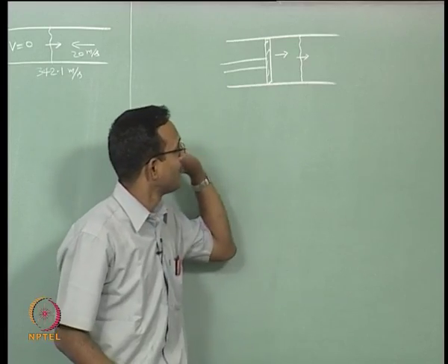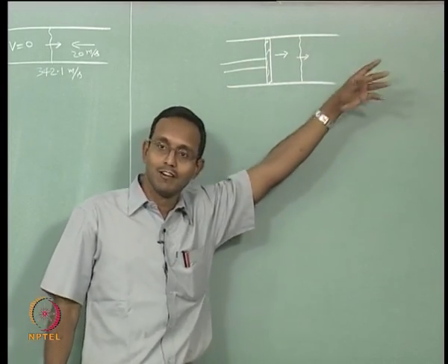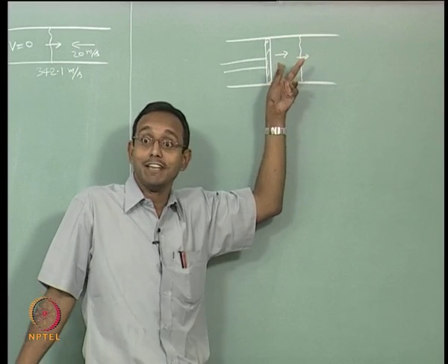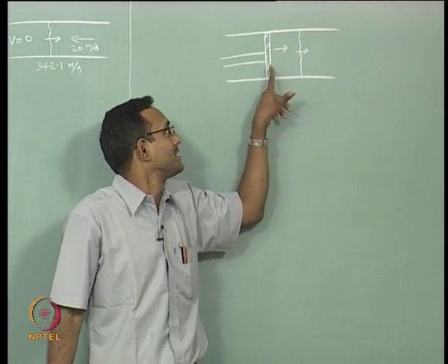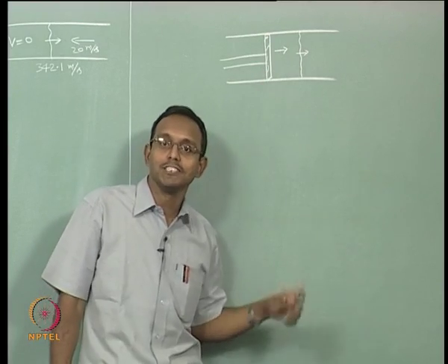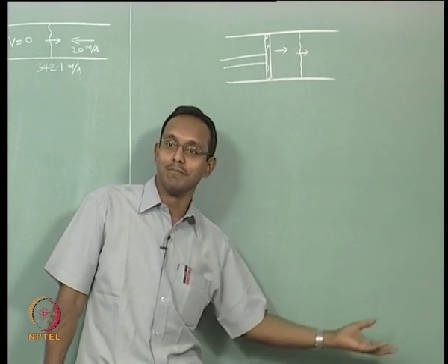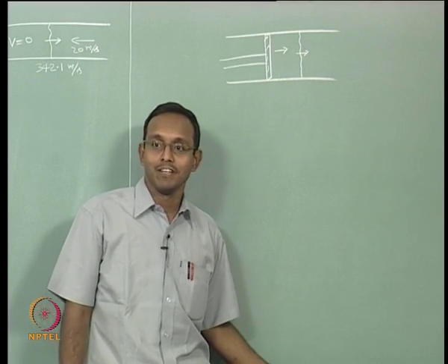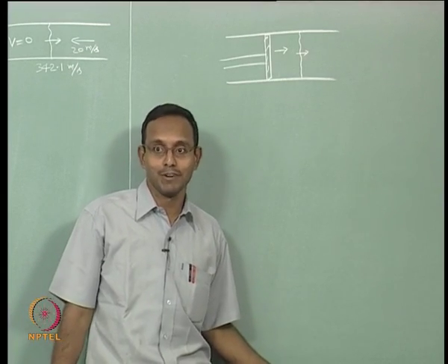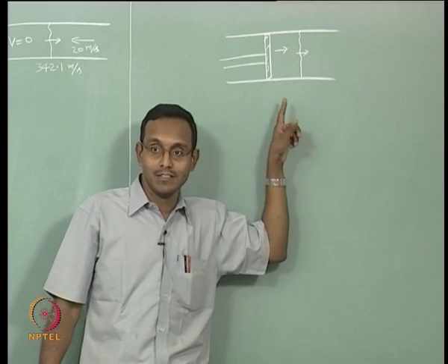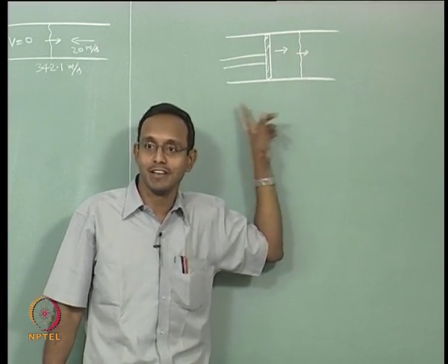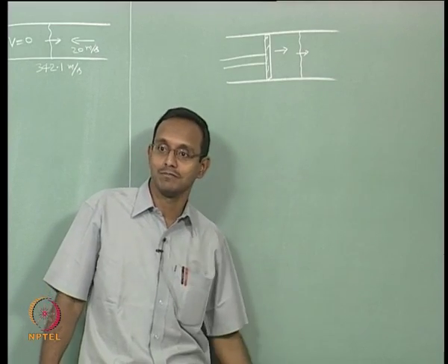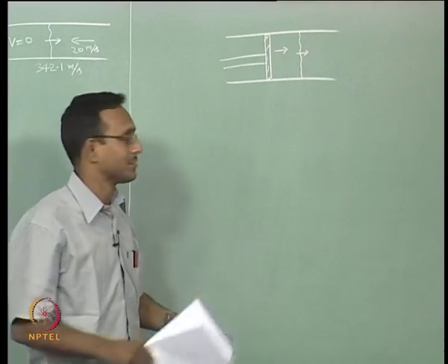The shock would have gone well past into the duct, and what we will see will be just a steady flow where the fluid has the same velocity as the piston, which is what our incompressible flow world will be talking about all the time. But if I am interested in the unsteady phenomenon from t equal to 0 onwards, then there will be a compressible flow field happening there, there will be a shock that will be created, and it will be going at supersonic speeds. Okay. All that is happening in there.